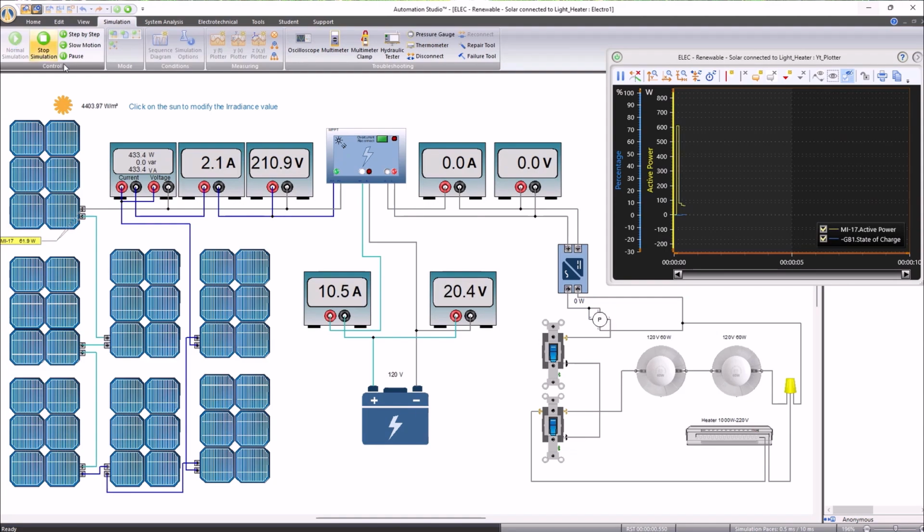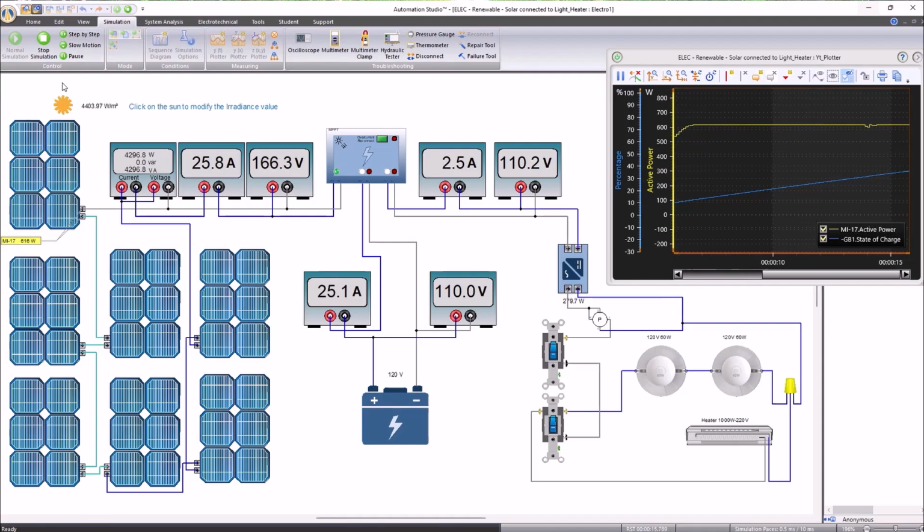We can see that even if we turn on the light switches, we don't have electrical current, because the charge controller is diverting the energy to the battery until it reaches an optimal charge level to then divert the energy to consumption. We also see the irradiance oscillations that we have previously defined to simulate the effect of clouds.